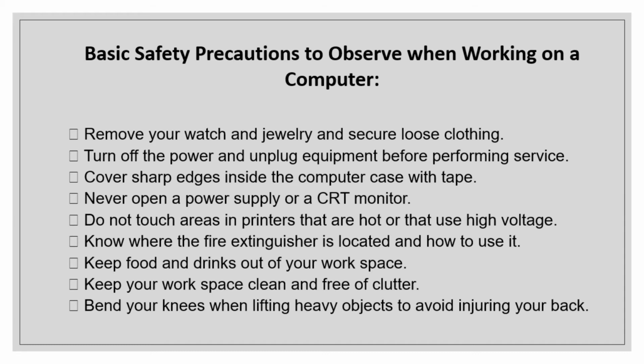You must also follow these basic safety precautions when working with computers. First, remove your watch and jewelry and secure loose clothing. Turn the power off and unplug equipment before performing services. Cover sharp edges inside the computer case with tape. Never open a power supply or CRT monitor.